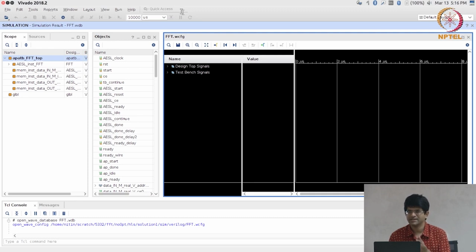So it effectively implements a memory interface between your C code and your Verilog code. This is not as trivial as it sounds at first, because C has no notion of a clock. There is no concept of time in the C code that you write, whereas the Verilog code fundamentally has to work only with a clock.